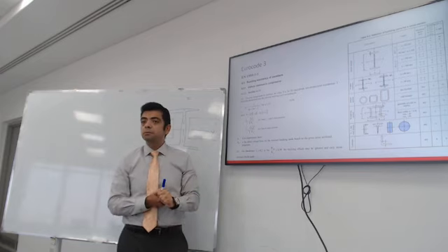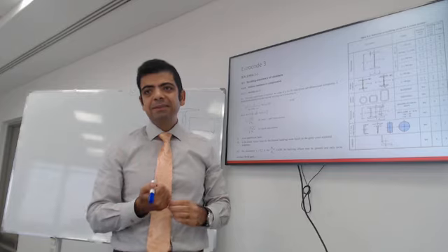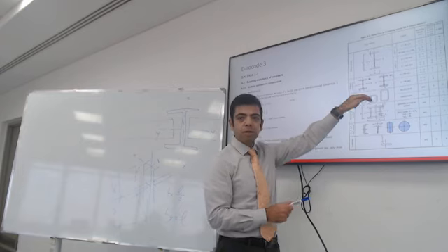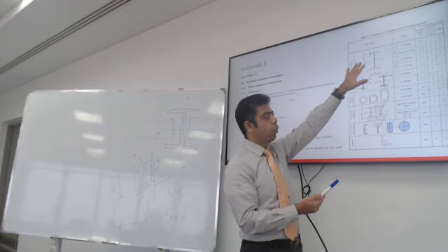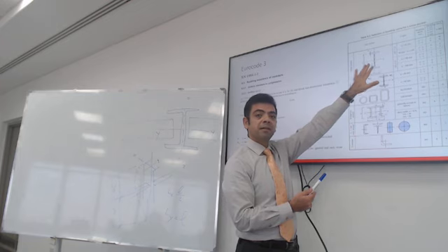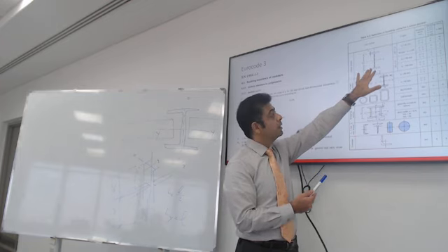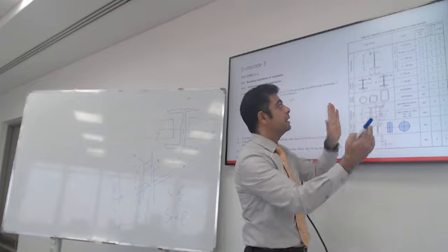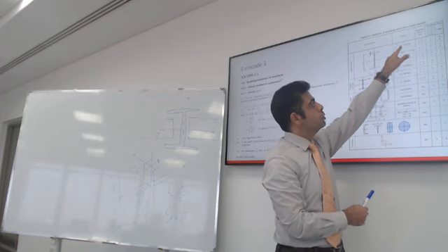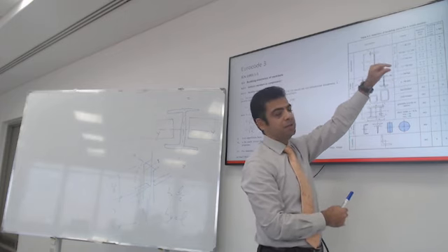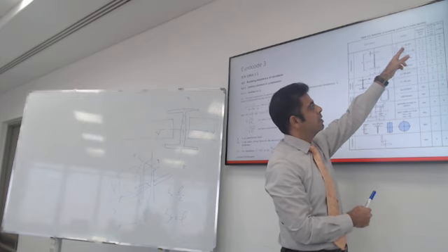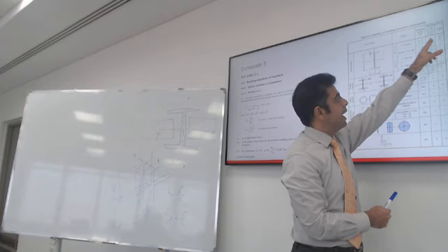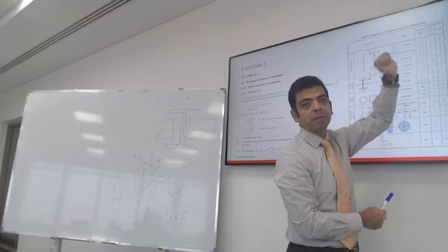Yes? I did not get how to calculate the imperfection factor. For the imperfection factor, you first choose a section of the column. Do you want to choose a box column or an I section? So let's say we considered an I section. Then you compare the depth to the width of the section. If it's more than 1.2, you check the thickness of the flange. Let's say the thickness of the flange is less than 40, then about the y-axis, you use curve A, about the z-axis, you use curve B. Does that make sense?